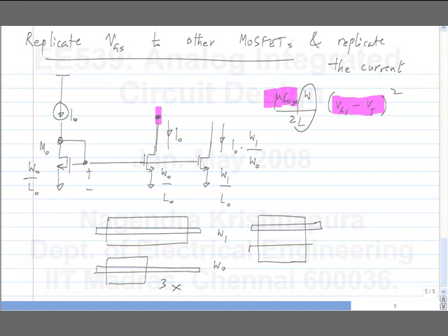So these are the gate fingers. You connect these two and you connect these two as the source, and this is the drain. Okay, so this is the layout of the MOSFET. This will make sure that matching is good. When you have an integer ratio, you can do this. When you have non-integer ratios, you just have to take the hit in accuracy. You cannot make it exact.